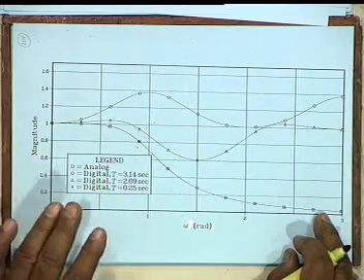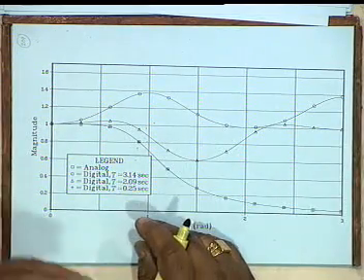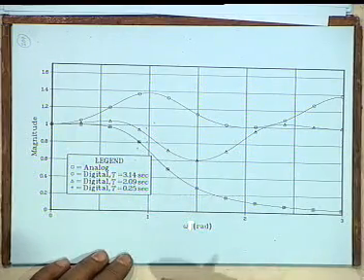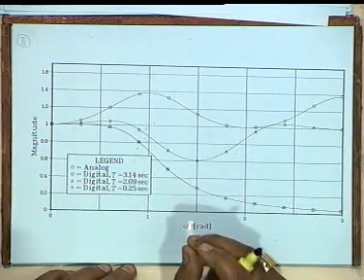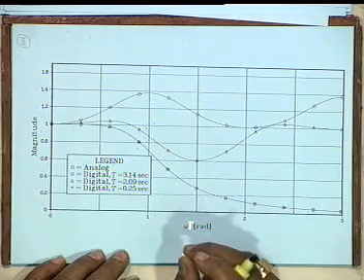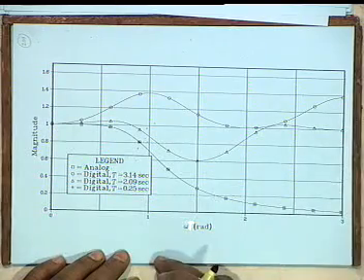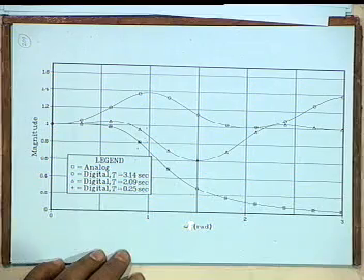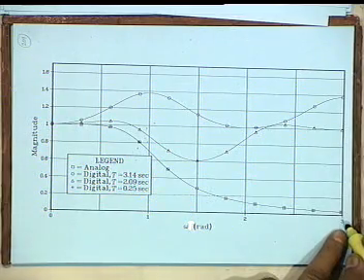Then you have to use MATLAB to be able to draw or watch on the monitor the transfer function, frequency response, and you adjust your capital T in such a manner that you get a fairly good match with the given analog filter.